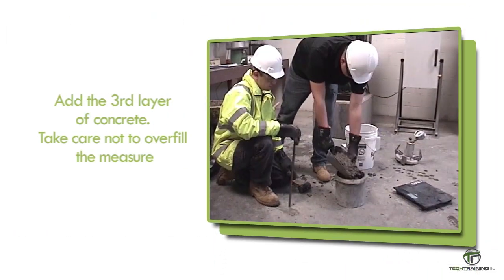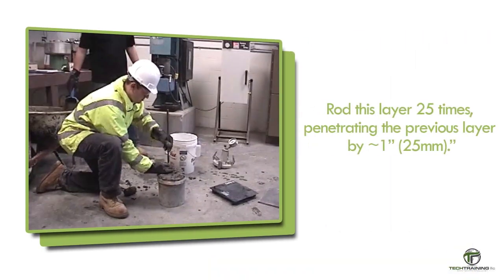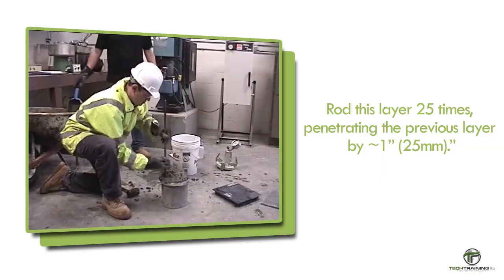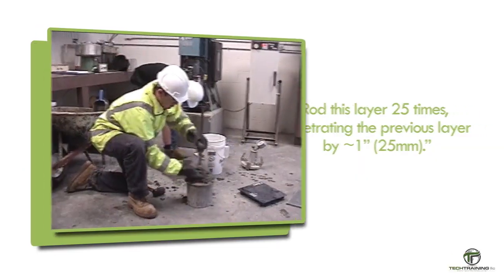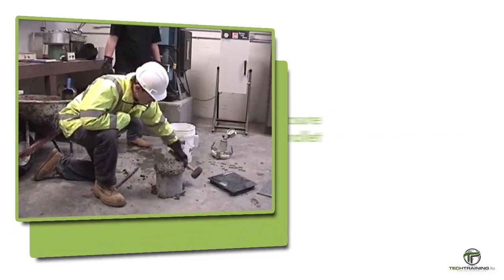We can now add the third and final layer of concrete, taking care not to overfill the measure. Rod this layer 25 times, penetrating the previous layer by about 1 inch, or 25 millimeters. Tap the sides of the measure 10 to 15 times with the mallet.